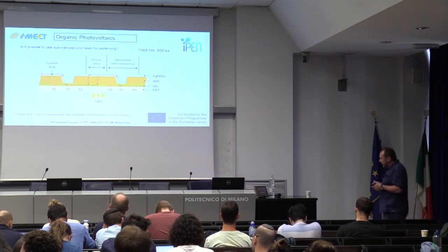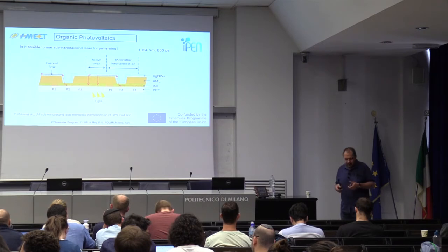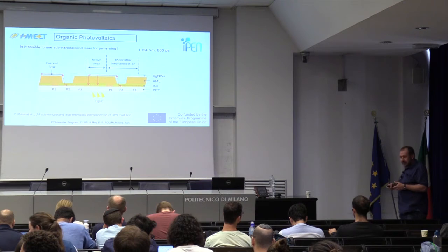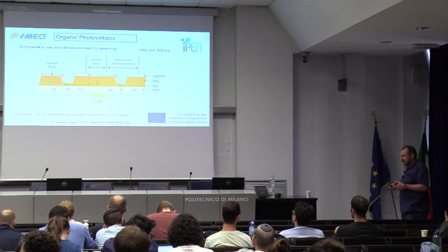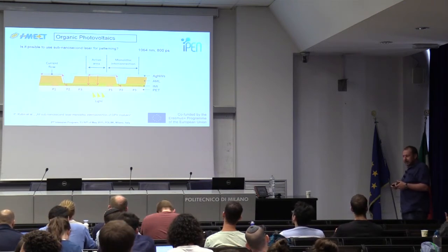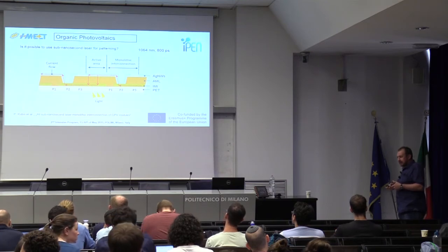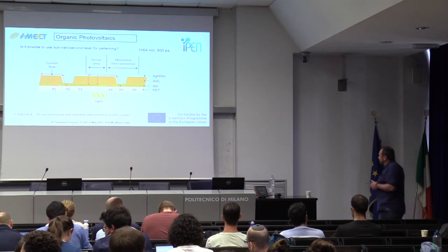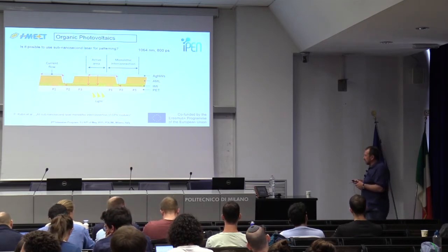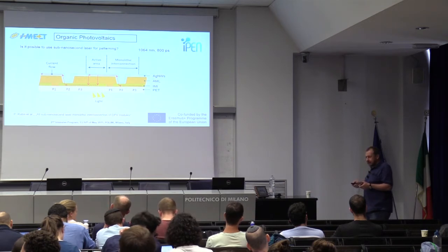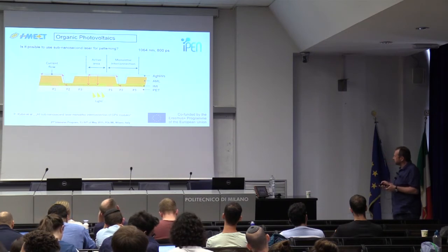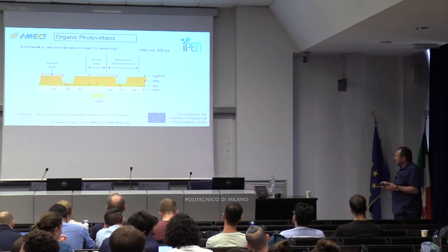Now here, this structuring works very well with femtosecond lasers. It works very well with green, typically 532 nanometer femtosecond laser, but these lasers tend to be very expensive and complicated, and so the question is whether it is doable also with an infrared laser, maybe pico or nanosecond laser. And here is an example of what was done at the Center of Advanced Energy Research.